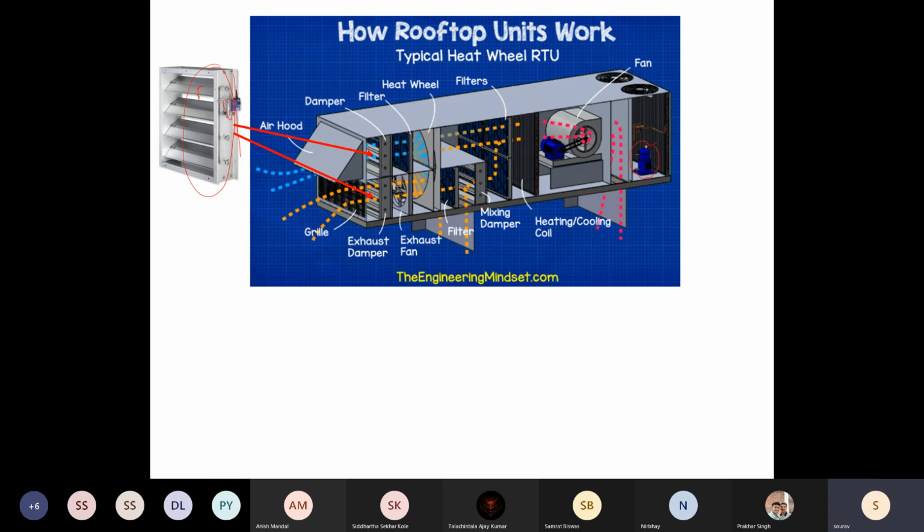Over here you see your compressor is there, a fan is there, and some coils are provided. So this is your evaporator coil. This is your condenser coil. And the compressor is there. Definitely there is a throttling valve, which is not shown in this sketch. So this is your entire refrigeration system: evaporator coil, compressor, condensing coil, and the throttle valve, which is not seen. In order to cool this condenser, you have these fans. This is isolated from the cold side.